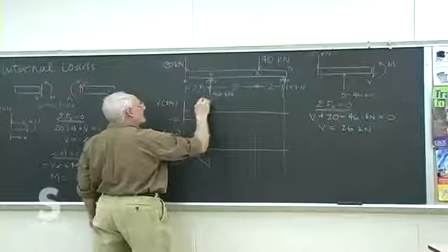So the slope of the moment diagram is the same as the shear. Remember too that the area of the shear diagram between any two spots is the change in the moment between those two spots. So all of these things should check. Even if you do get a minus sign wrong somewhere, you should be able to catch it with these checks that we can do.